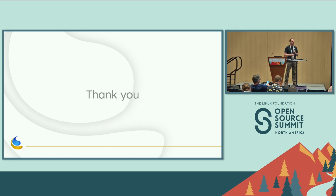So I guess just follow what other people do, look at other device tree sources that are out there, and get a good feel for what to do. Yeah. Looking at similar devices is always the best thing to do, because we always want to reuse the same properties for the same thing, so that we're not reinventing new things every time. Even if it's a custom property for just one chip, a lot of times there'll be another chip that does pretty much exactly the same thing, so we want to use that same custom property in the same way everywhere.